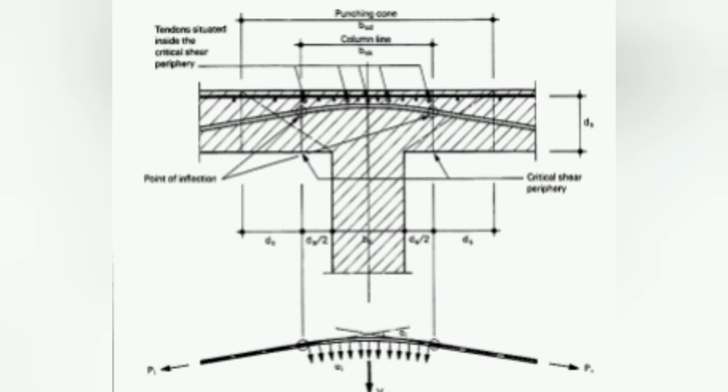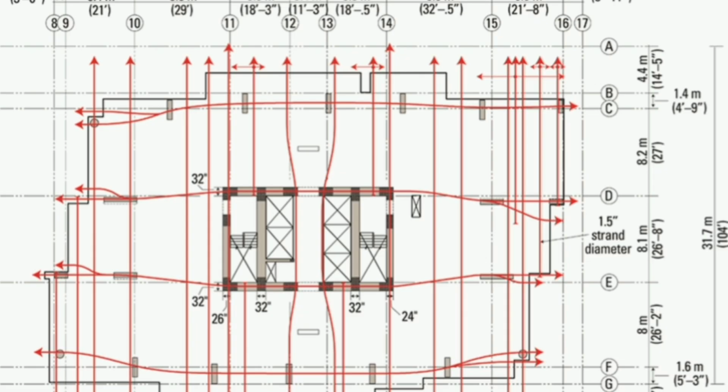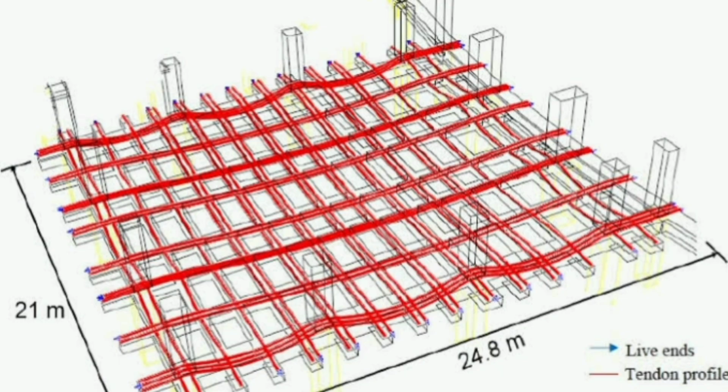The benefits are monumental: significantly reduced deflection, thinner slabs, and much longer spans. Post-tensioning can be applied to flat plates, flat slabs, and band beams. It's the preferred method for large office buildings, condominiums, and structures on problematic soils where controlling deflection and cracking is paramount. A crucial pro tip for any project involving post-tensioning: the anchoring and stressing operations are highly specialized tasks that must be performed by certified technicians.